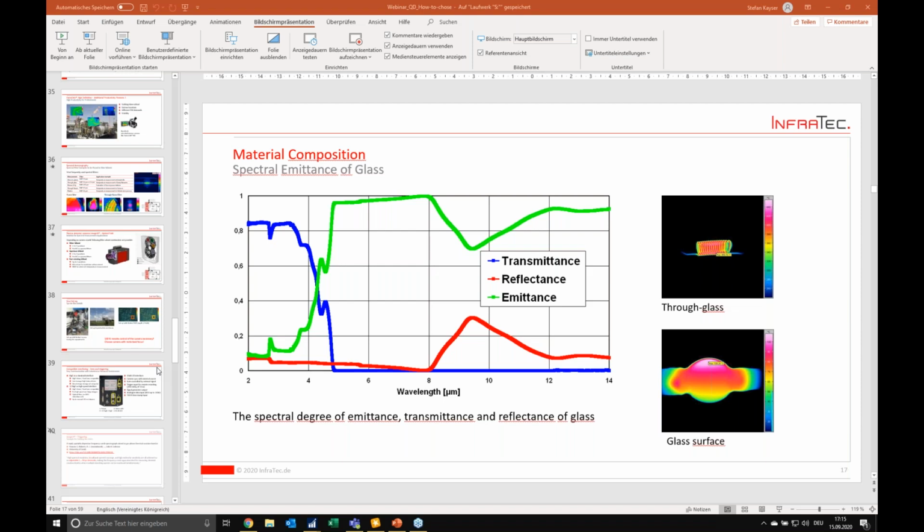So normally the IR radiation beam runs through the lens and hits the detector in a quite straight way. But what we do is we influence this beam length, so that we shift such an image by half of a pixel, so by a sub-pixel range, and this slightly shifts the orientation of the image on the detector.